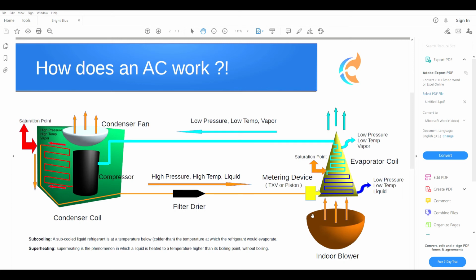So it's really important when you install an air conditioner. If you haven't installed that furnace or the air handler yourself, if it's an existing one, just go there and make sure that the airflow setting is right for your new air conditioner.